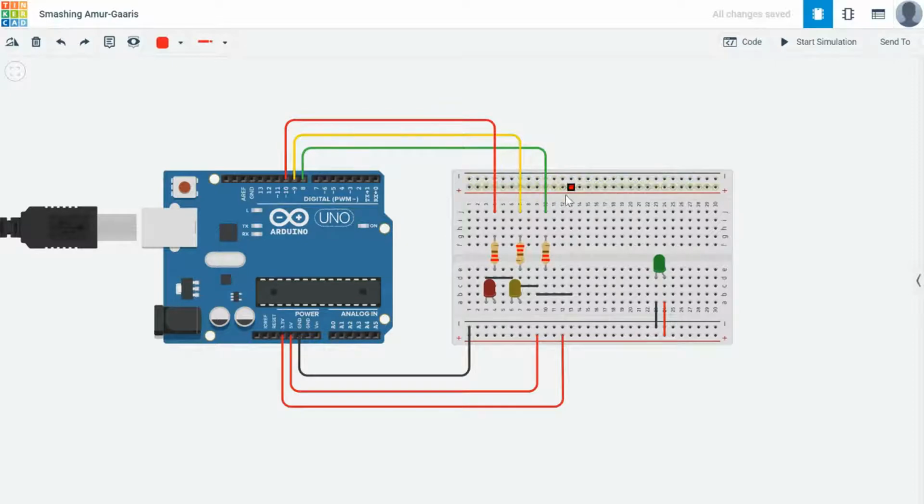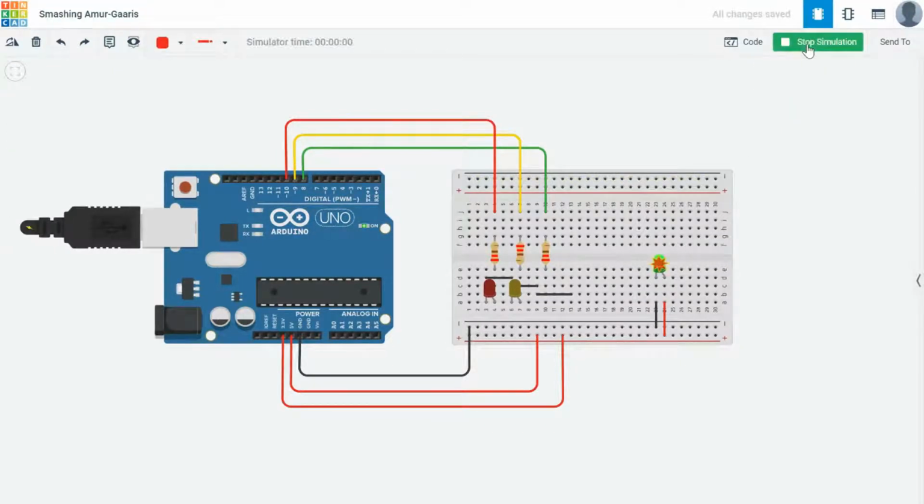So it doesn't matter about the code for this, because as soon as we turn this on, it will inject the voltage into the board. So let's start simulation. Yeah, there you go. It wasn't a massive explosion, but you get this big red explosion icon, and it says the current through the LED is 483 milliamps, while absolute maximum is 20 milliamps. So we've just put 483 milliamps through that LED, and it should only be 20.